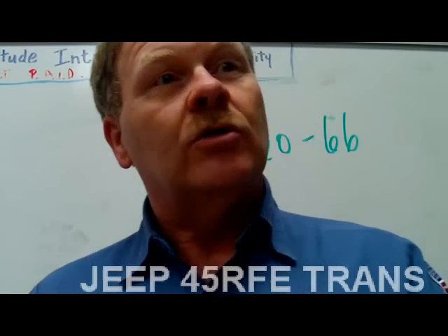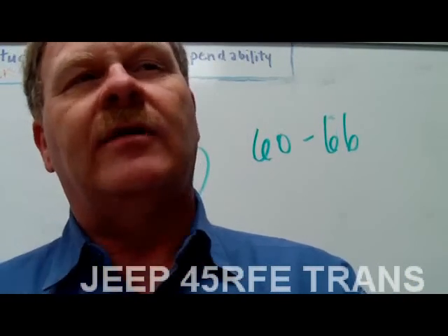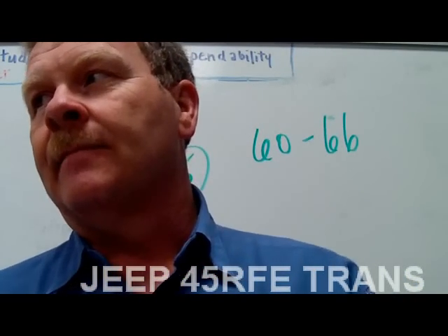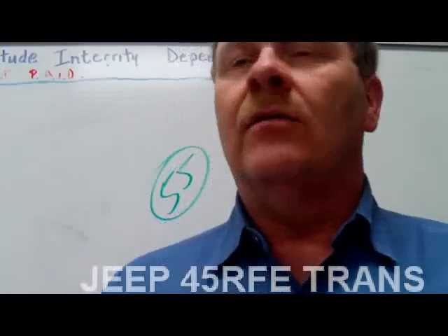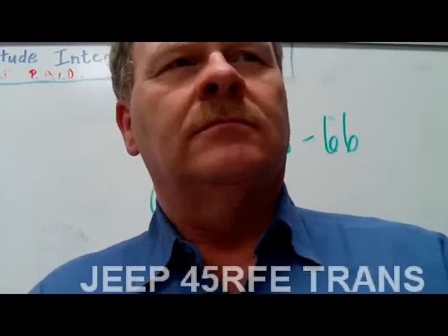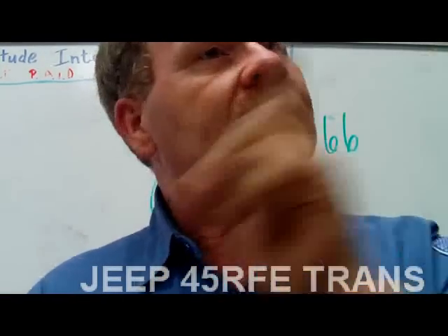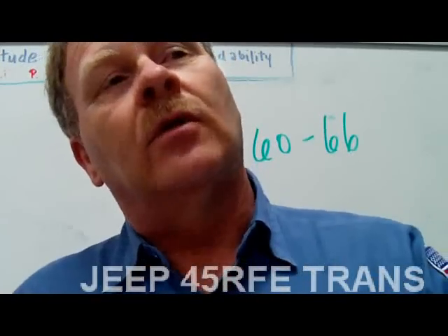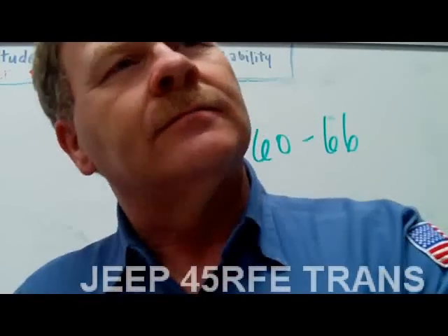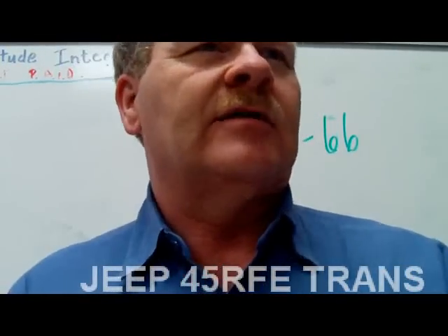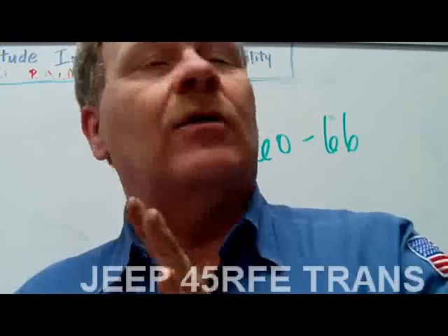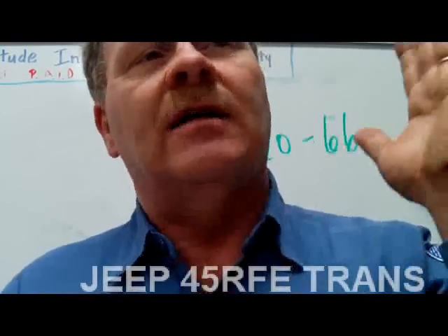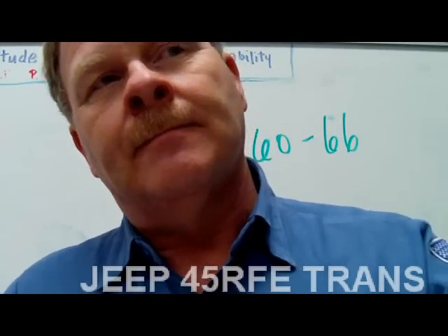We had decent cooling, and where does the heat come from in an automatic transmission? Who can tell me that? Where's the heat made? In the transmission? No, it does not. Not in the transmission. Yeah, the heat's made in the torque converter, which is technically part of the transmission, but down inside the transmission, that's not where the lion's share of that heat is made; it's when that torque converter is shearing the fluid. See what I'm saying?